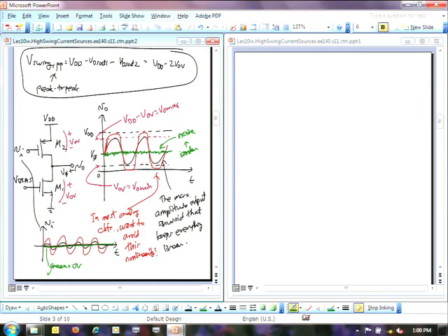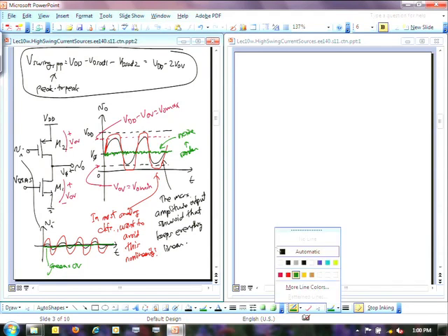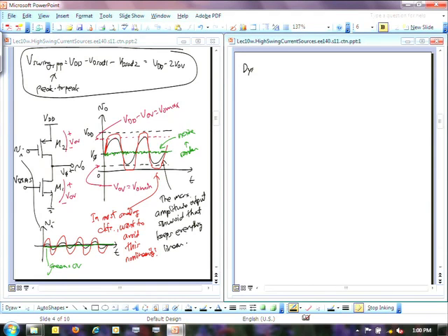And so it turns out it's difficult to design a circuit that can both pull something out of this noise. So say we had an output way down in this noise and be able to amplify to very large signals. Okay, so that's why we define what's called the dynamic range. Okay, so the dynamic range ends up being sort of the maximum output signal you have divided by the maximum output noise that you would get with a zero input into this. Because the maximum output noise is the minimum signal you can get. And so this is one thing that analog designers care about a lot. And you'll hear it again and again.